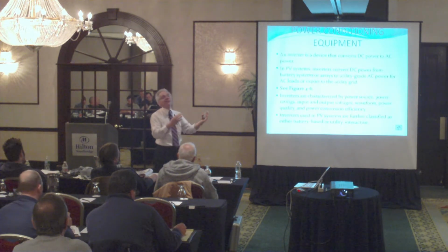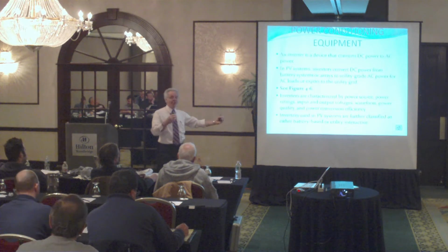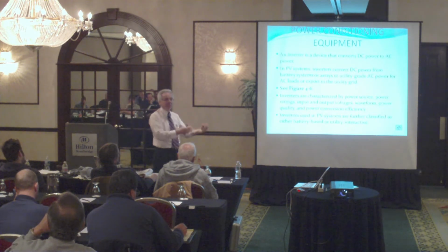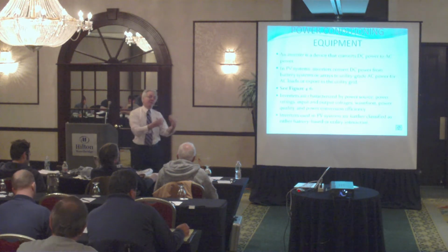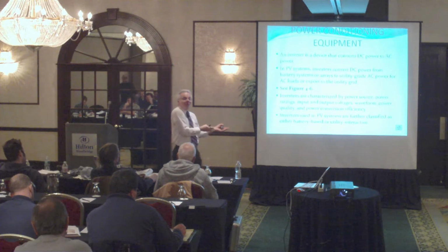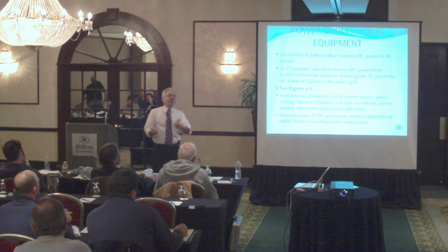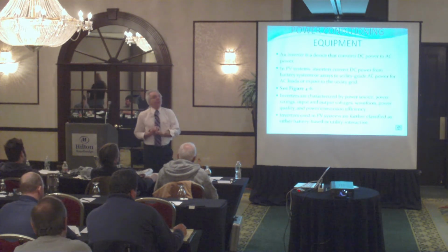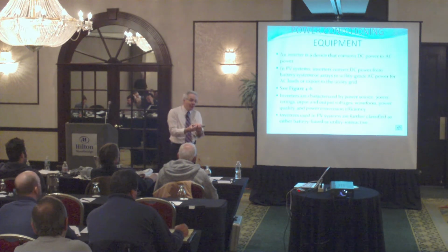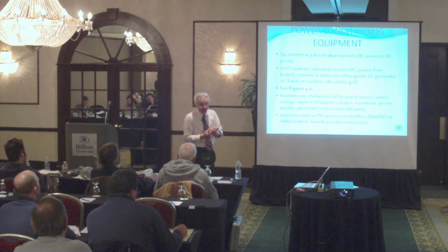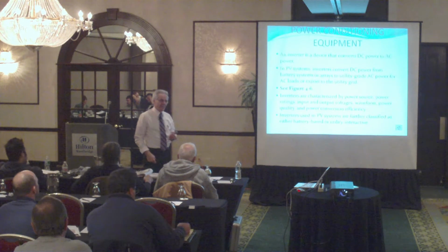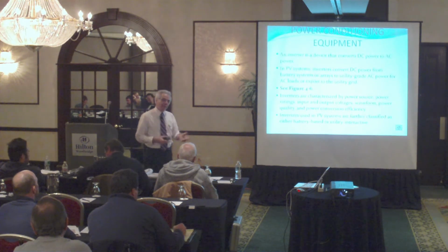How much power, from the input to the inverter to the output of the inverter, do they really lose? How efficient are they? 90%, 95%? Because the rest becomes wasted energy. It takes us a long time to generate that power, and all of a sudden, because of the inefficiency of the inverter, we're losing a lot of it. So a lot of effort is going into inverters, so that they become very efficient. I think the efficiency of inverters now is probably over 95%.